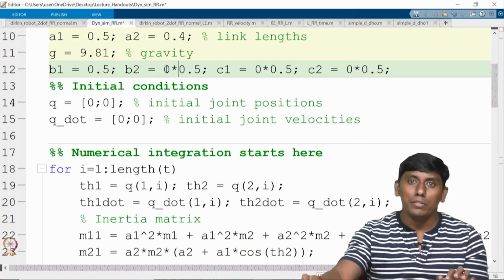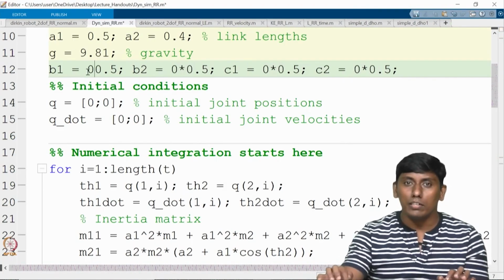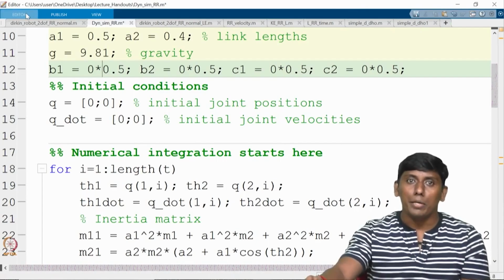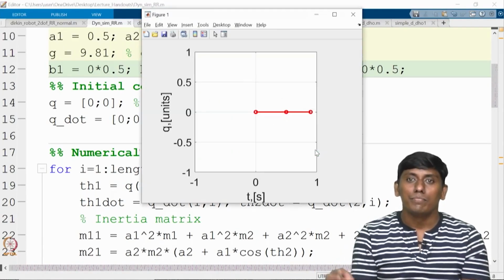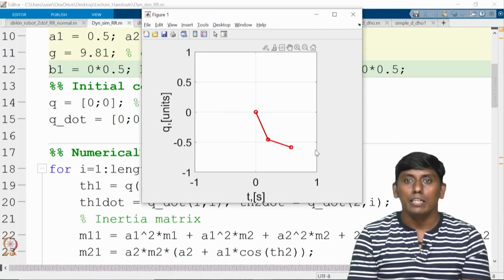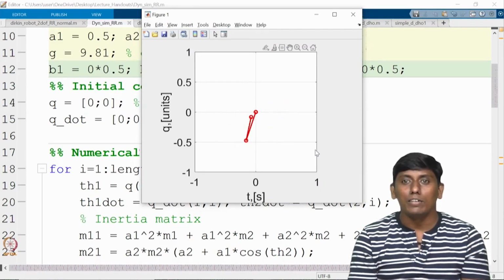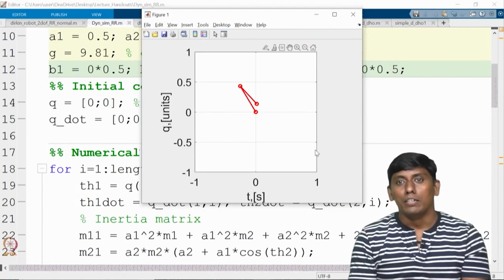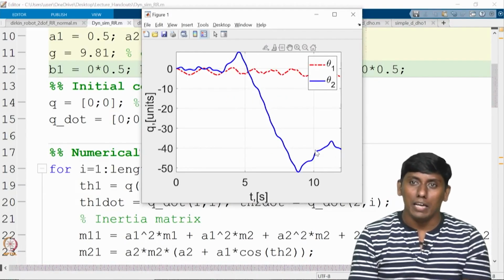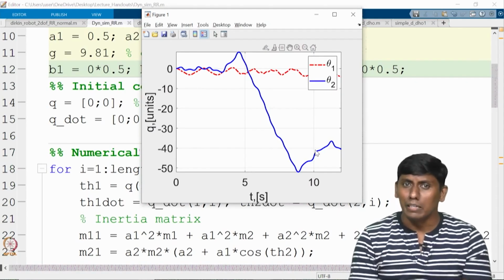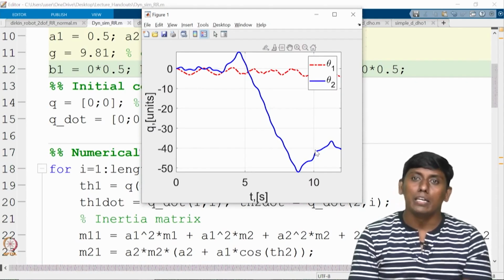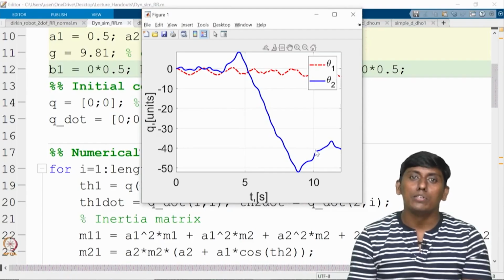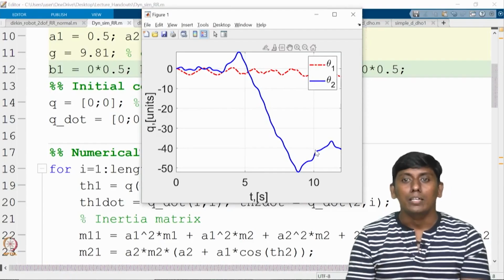Whether that marginally stable system, in the sense of a continuous oscillation with equal intervals, is happening or not, you can see. Okay. Now you would have seen that it is getting an oscillation, which is completely not acceptable in real time. If you leave it, the system will not propagate. So now one can see why this is happening. It is very simple, because we have done a simple numerical integration. This particular phenomenon is not observable with a simple Euler integration.